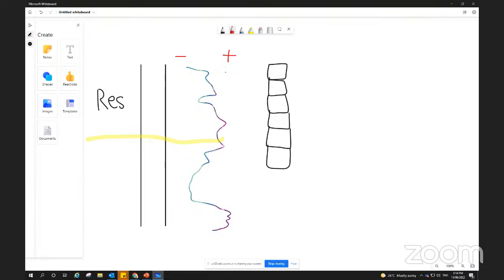For example, this is the average. I can see there's an increase in porosity downward, so I should have here an average of 10% porosity, here 15%, and here it's much lower, so I say 5%. Then it is increasing, so I expect let's say 18% or 20%.